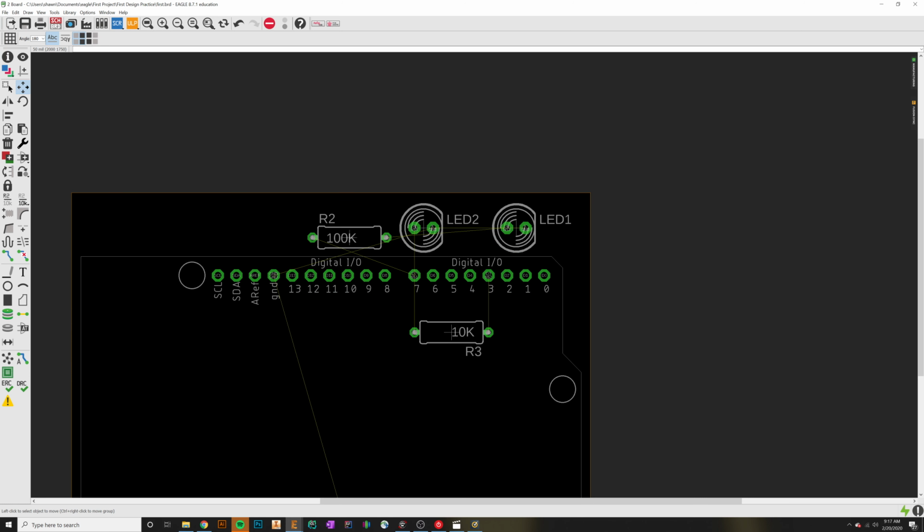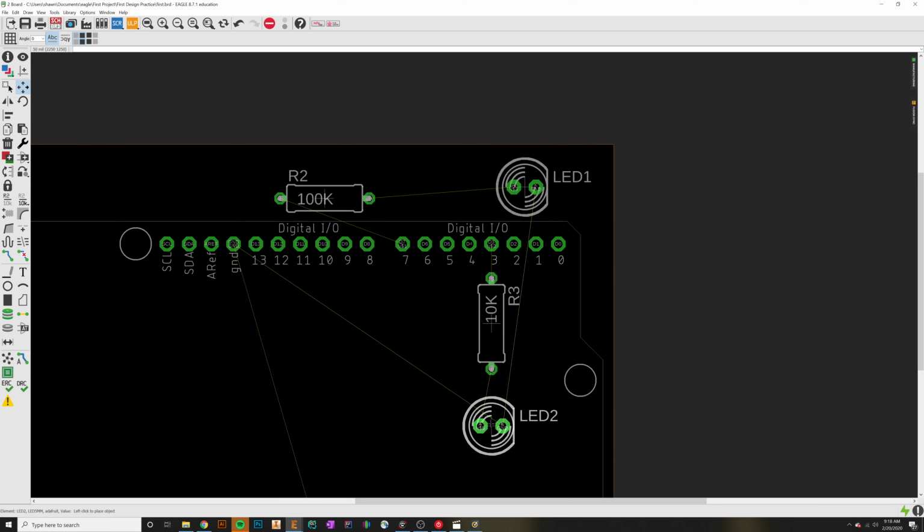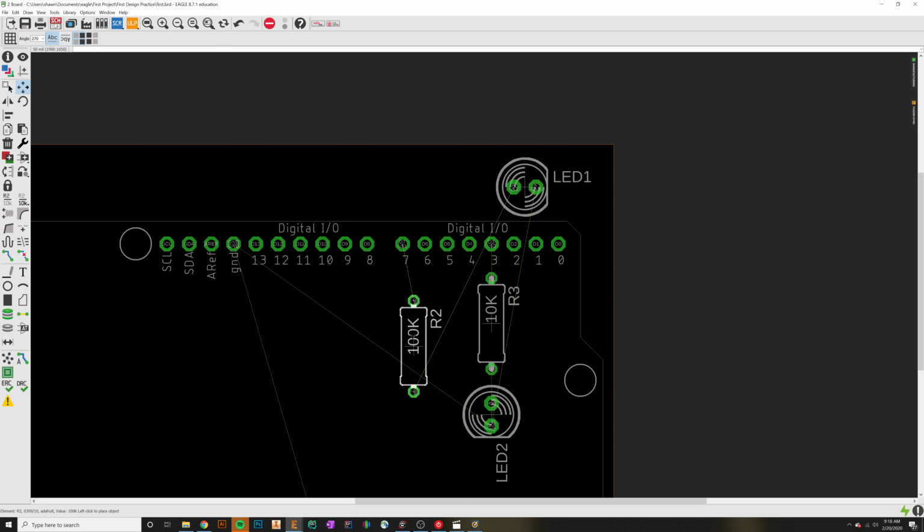When I go about optimizing the position that I need the component to be, I'll try my best to put it next to where it needs to go. You can see that this little pin right here needs to connect to pin 3, so putting it nearby is going to make it easier to route. I see that I also have this second LED here, and I could do the same thing. And then I'll do the same thing over here.